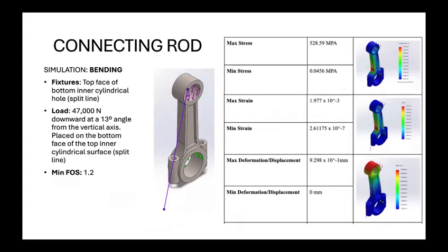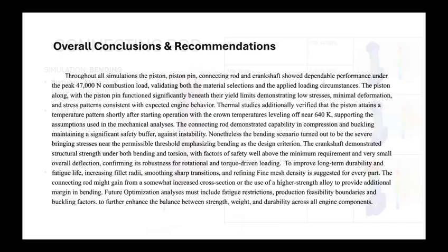Finally, the most severe case was bending, where the same 47,000 Newton was applied at 13 degrees angle. Stress rose to 528 megapascal, giving a reduced factor of safety of 1.2. This tells us bending is the governing failure mode for this component.